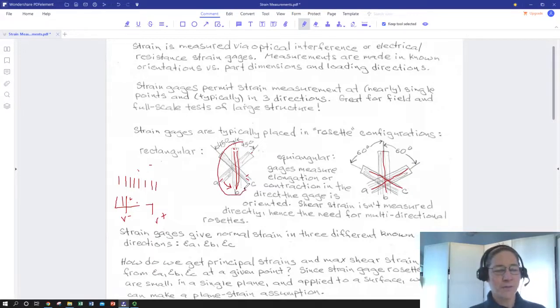So that same directional relationship between the strains of those two points will carry over into the Mohr circle, except double the angle. So the point representing the orientation for B will be 90 degrees counterclockwise to whatever we determine it to be for A. Which brings us to the last most important point.